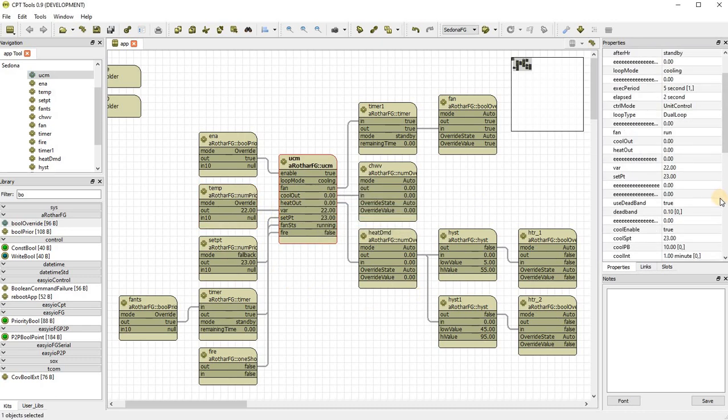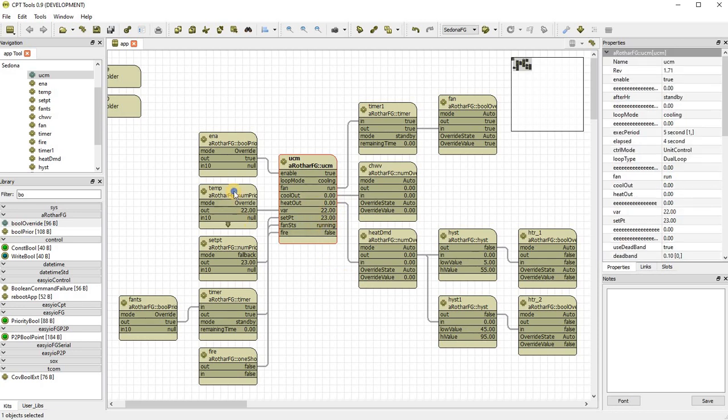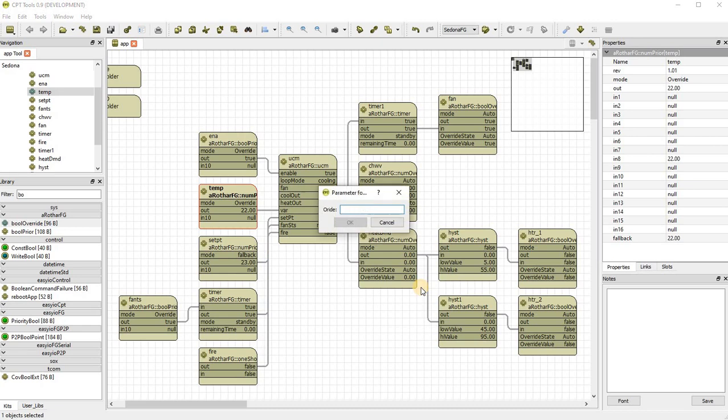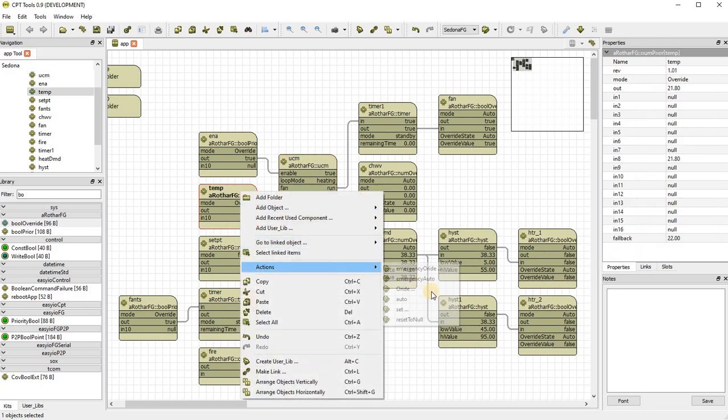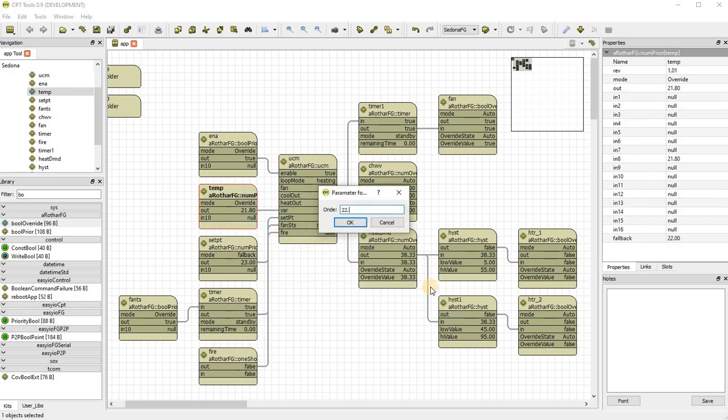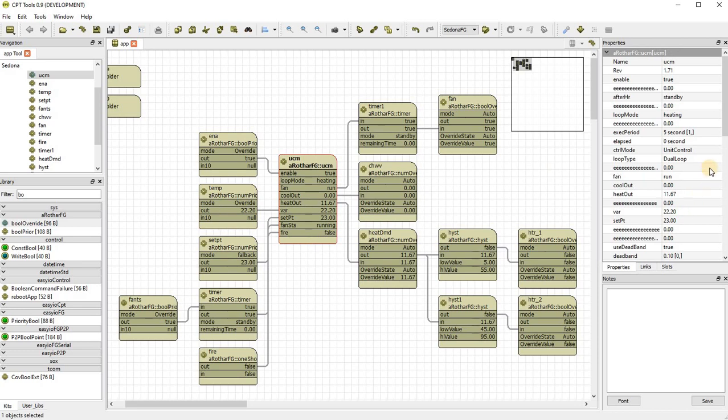Again, while it's in there, it's probably not going to do anything because the deadband will be active at 0. Yep. So let's go 21.8. Wait for our loop to expire, and then we're at a fixed output, which it will stay at through set point. And when it flows out the other side of set point at 22.2, it'll be different. So the deadband will screw up the proportional band control, but you know, it's up to you how you want to control that.